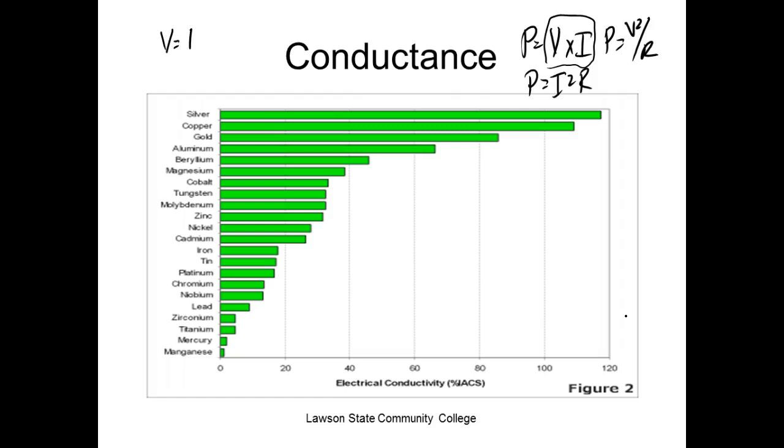So here they're trying to run all these power cables hundreds of miles, and these towers have to support that metal, right? If they use aluminum, it makes it lighter, so the towers they're running this high voltage on don't have to be as strong, and plus it's a lot cheaper. But it oxidizes and it has a big coefficient of expansion, which means it changes.